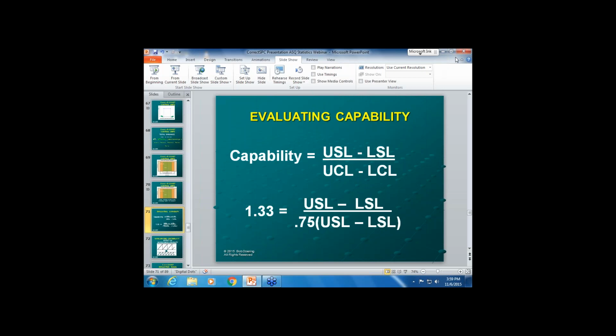Well, some of the customers say PPK, forget CPK, but you know, okay, what? More often than not, you're only doing it to satisfy customers. Here's the problem with capability. When you calculate capability, you're using one number, 1.33, a simple number, to describe the variation that you expect to see over the lifetime of a product in a process. Really? What a magic number that is.